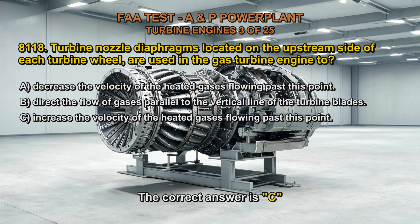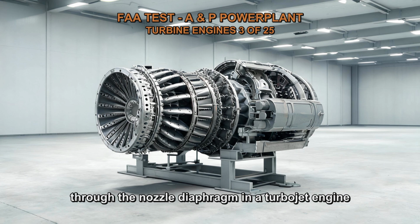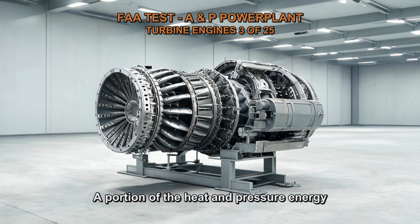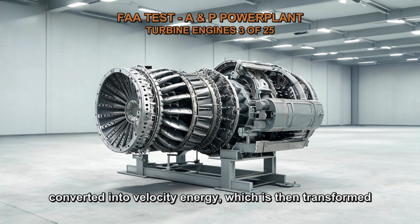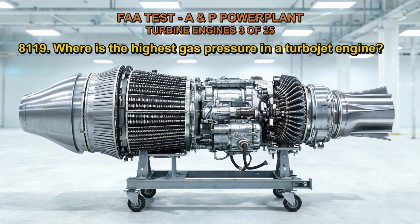The correct answer is C. Increasing the velocity of the heated gases flowing through the nozzle diaphragm in a turbojet engine is one of its tasks. A portion of the heat and pressure energy that is used to accelerate this gas is converted into velocity energy, which is then transformed into mechanical energy by the turbine rotor blades.